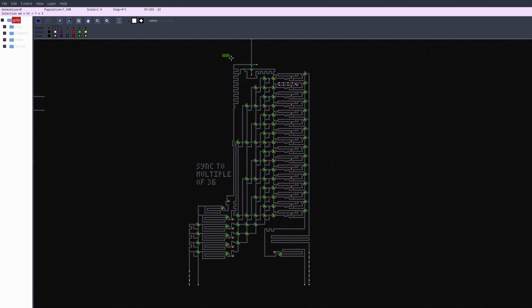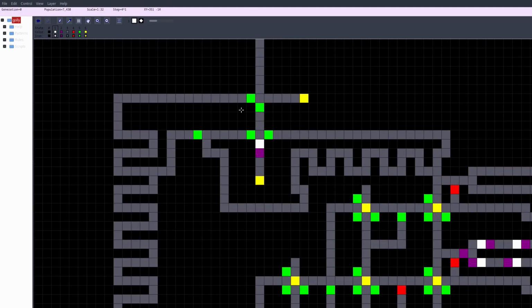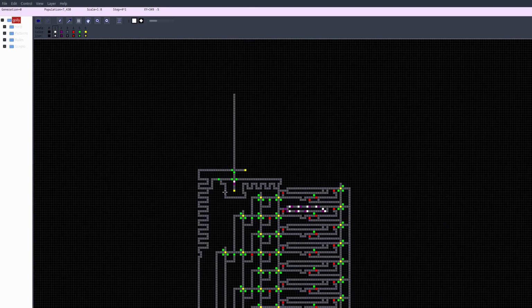This is some stuff for fixing the output of the device, since when the read signal comes in, it actually reads the upper bits of the register and then the lower bits. But everything in this processor is middle endian, so we have to correct this at the output using some OR gates and clever delays.